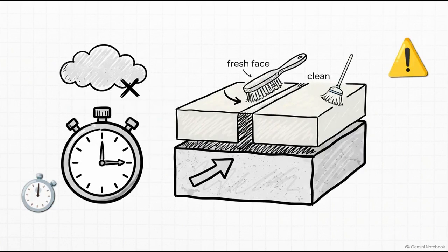Equipment breaks down, concrete trucks get stuck in traffic, or a sudden thunderstorm rolls in out of nowhere. This brings us to unplanned interruptions. If a delay goes on long enough for the material to set, the resulting interface can no longer be treated as a fresh layer, period. It must be treated as a construction joint. The crew cannot simply restart shooting over a hardened edge without doing the required prep work.